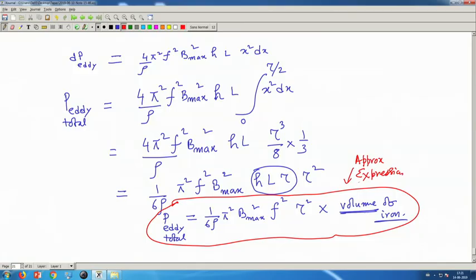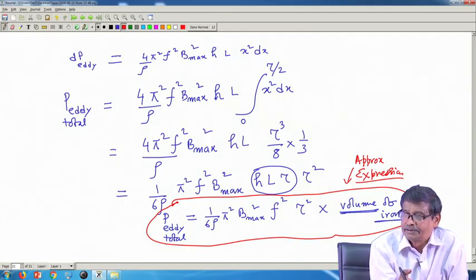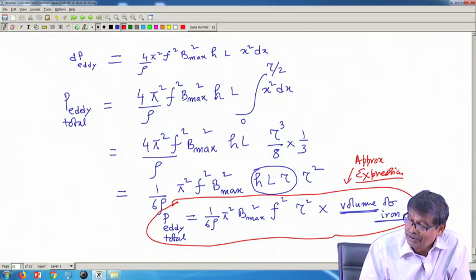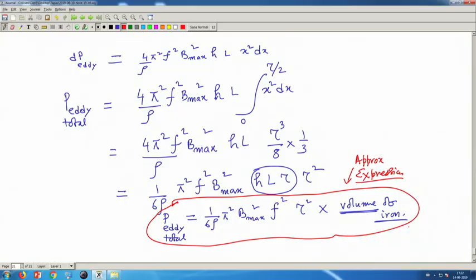For eddy loss, I know many things. Eddy current loss depends upon the maximum value of the flux density squared, supply frequency squared, and thickness squared. Remember, what is the fun of expressing it in this way? It is because I have considered a single plate while deriving this. There will be multiple plates, and it can be expressed in this way. Therefore, if you have used more plates, then the total volume is to be multiplied. That is also crucial to note.